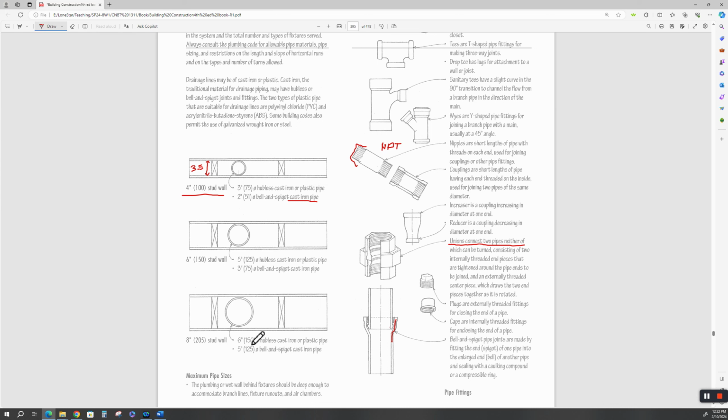So you've got to be careful about what kind of soil pipe is coming down. If not, then you're going to have to build a pilaster out here out of sheetrock just to hide the pipe. And in some cases they do that. In some cases for structural steel buildings, those sheetrock gypsum board casings that you see abutting out of the walls to hide the columns.